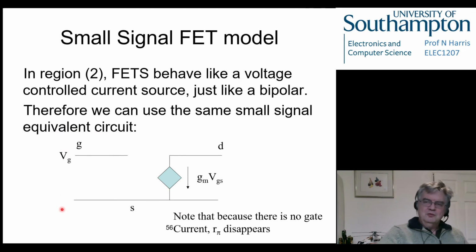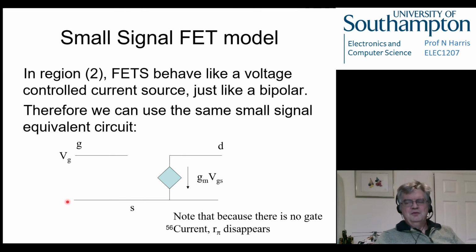So although FETs look very complicated and they've got lots of maths and things associated with them, if we just start looking at the flat region, this is the model for it. And this is easy to use compared with the bipolar model because there's nothing connected to this terminal here. It's just an open circuit, which is great. I don't have to worry about this resistance.